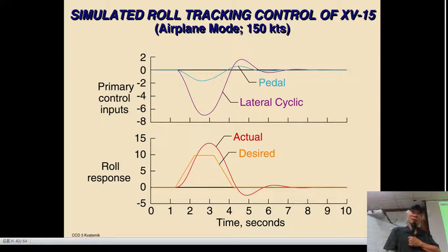Some systems are not controllable. Even if you give them a desired eigenvalue, you may not be able to achieve it. So for a controllable system, yes, the desired eigenvalues are achievable by the pole placement technique. But for your desired eigenvectors, it doesn't matter whether the system is controllable or not. Normally, they are not reachable. Okay.